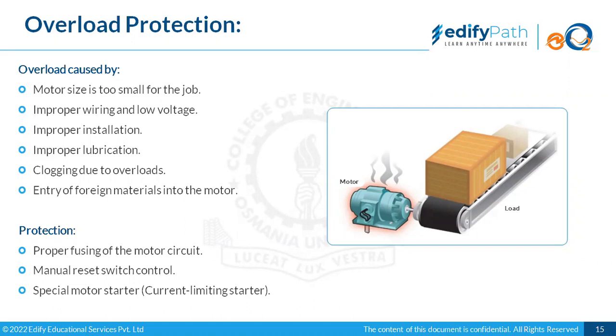Motor size is too small for the job. If our load is higher and we have used a small motor, there would be an effect on the motor. So sizing of the motor is very important. We should take care of what process we have to run, and accordingly we should size and select the motor.